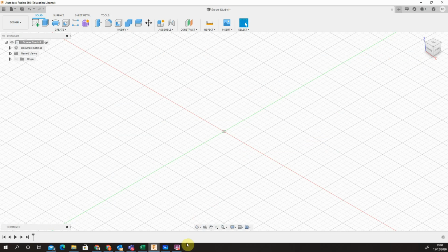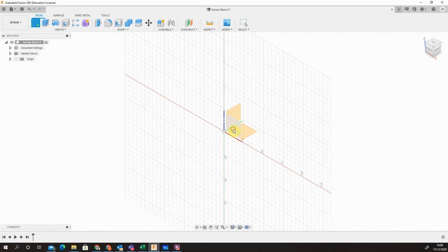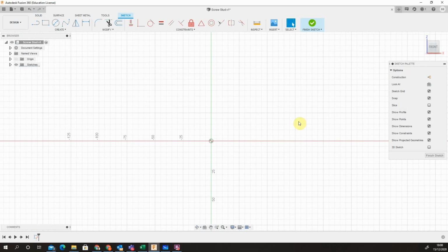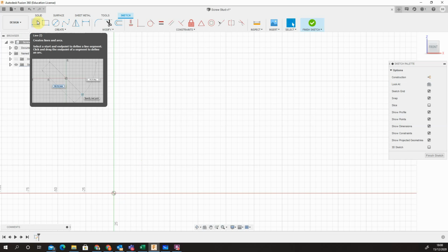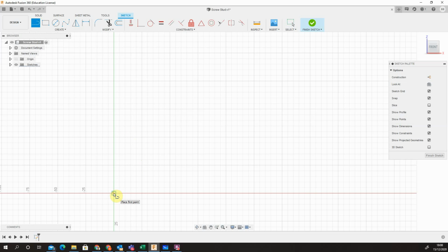So in Fusion, I'm going to do exactly what is on my model. I need to draw a sketch. I'm going to select the front face, which will plane round, and pan just to get my datum to the left hand edge. All I'm going to do is half the revolve to build my axis. So I'm going to draw my line, which is 70 tall. Another line using the L hotkey command. It's 12mm diameter, so 6mm radius.